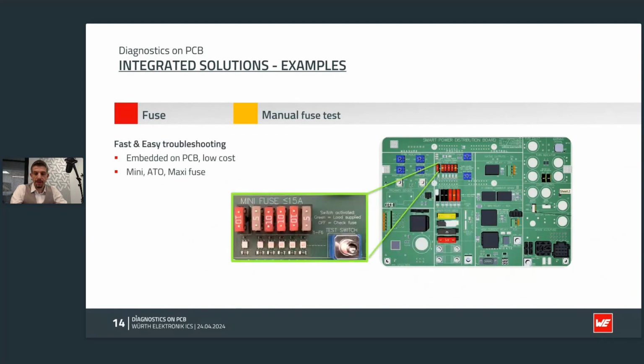Another option, with which we equip many of our customers' boards, is to have a fuse test located on each fuse of the board with a button to activate the LED. Nothing fancy here, just switch the LEDs to the ground. Once activated, all the fuses which are OK and powered will light, and you will easily see the blown fuse without any manipulation at all, other than the push of a button. Upon request, this button can be either a switch, toggle, or momentary, or a push button.